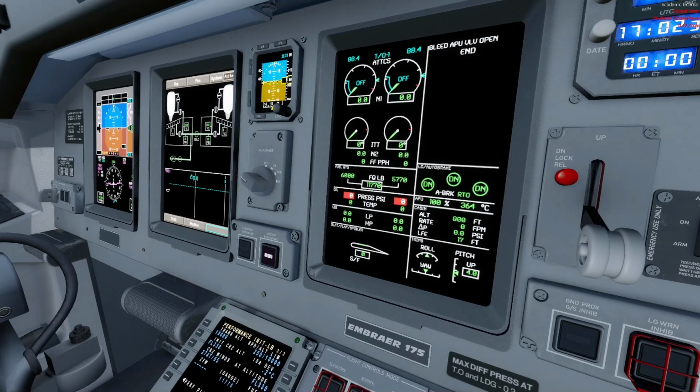but it may just make us too heavy for landing on that runway. Then we might consider burning some fuel, but in some cases, when the runway is extremely short, it may just make us not good to land, so we might need to divert because of that. Just a small, interesting operational chain of events, because we pick up like 5 seconds of light rime ice on the climb out of Chicago.